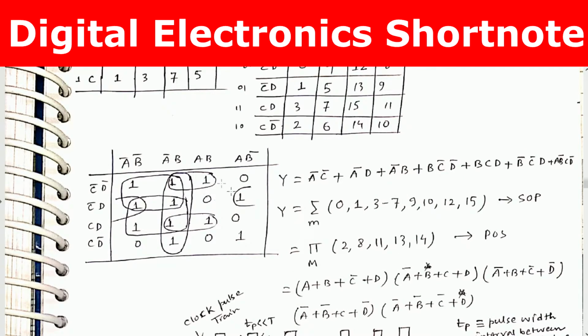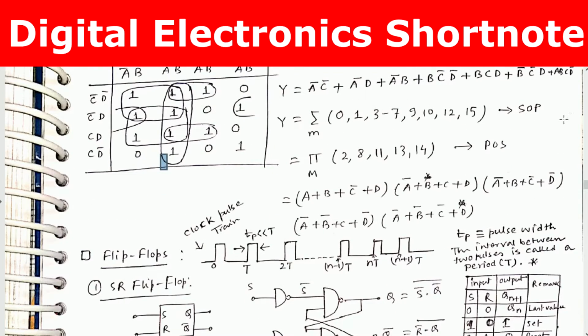When 2 at a time are selected, it's called a pair. When 4 at a time are selected, it's called a quad, and when 8 at a time are selected, it's called an octet. So we have to try to cover the maximum. Look, here we can cover four 1s, so it's a quad. This is a quad. But this is a pair, this is a pair, and this is also a pair. And accordingly we get this result.